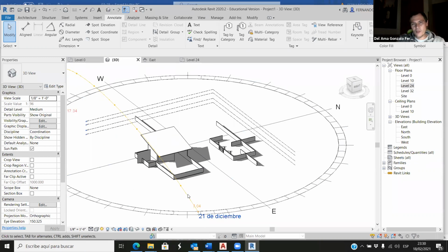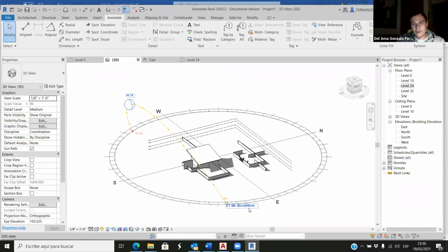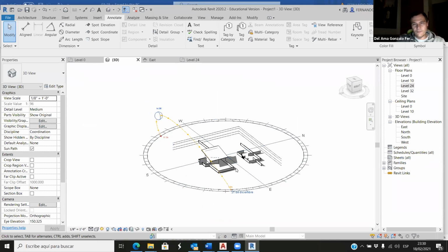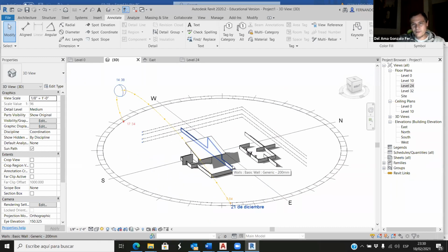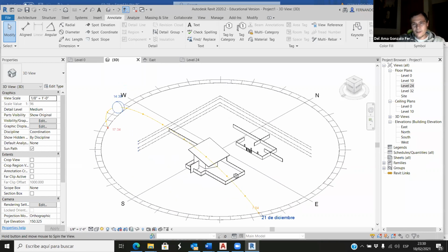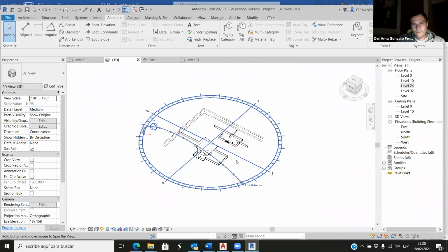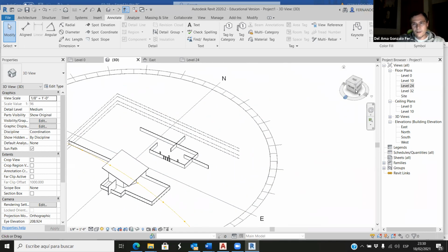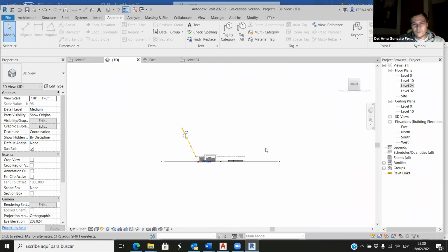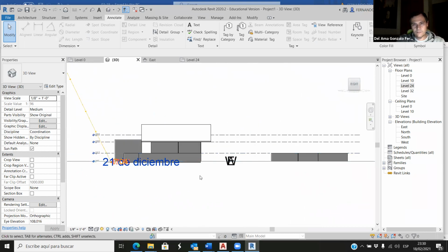And then if you want to visualize things in Revit, there are a lot of things we can do, and working with perspectives in Revit is interesting. As you can see, by default, we have axonometric views. But if we select the front view, and then you right click here on this cube, okay?